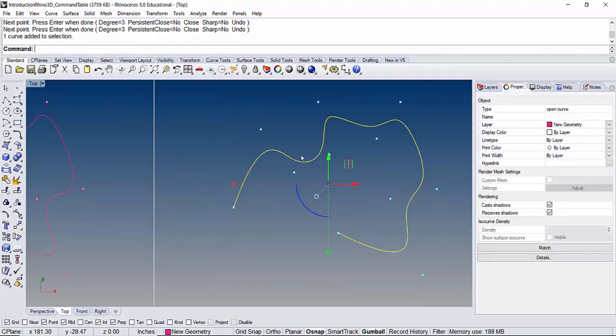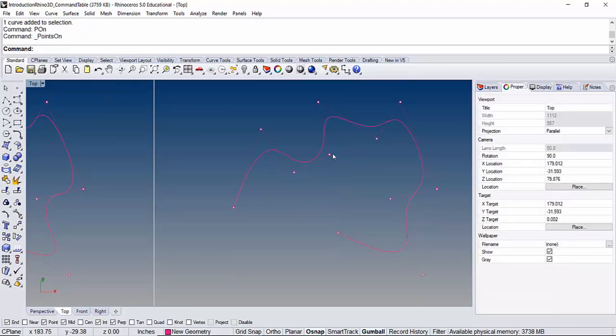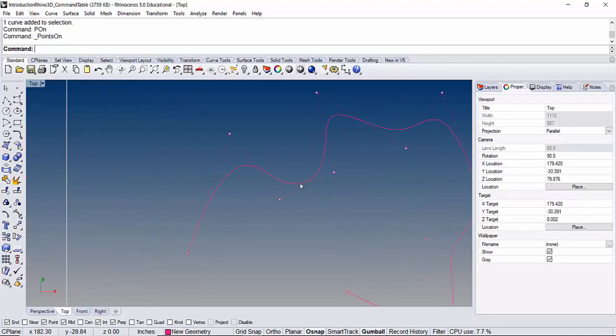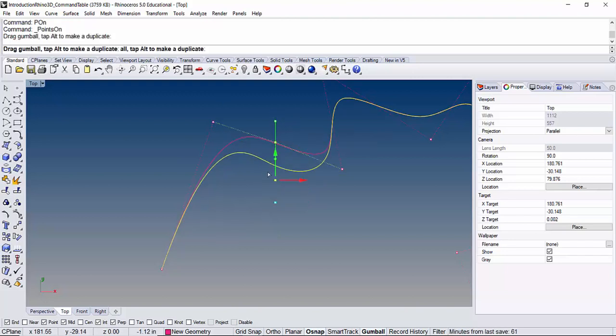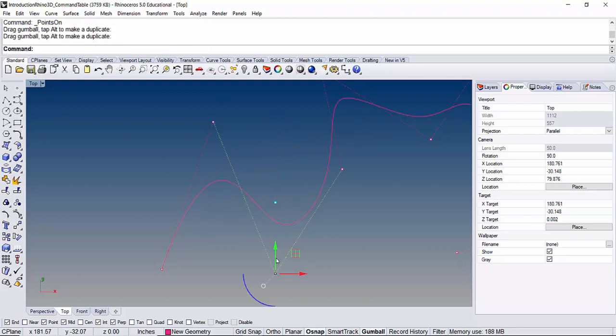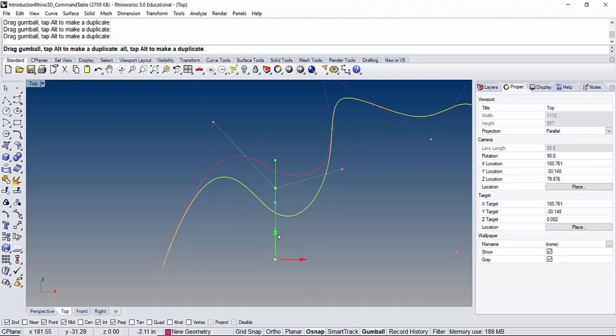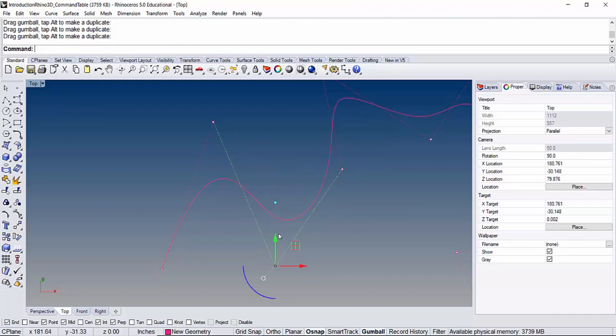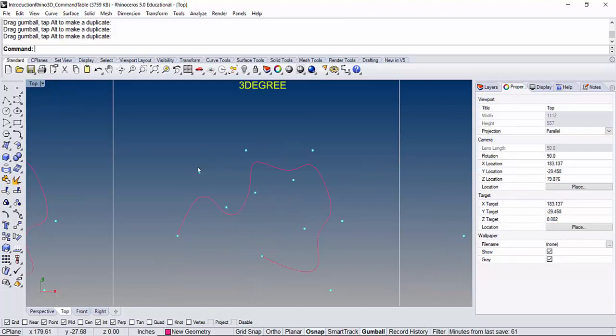So because a 3 degree, if I turn on the control points, it's smoother than a 2 degree, actually for every segment, there's 3 control points that are significant to the shape. So if I start to move them around, you could see that your geometry is not really going through these control points, but it's like when you're controlling a doll with a series of strings, right? When you push one, all the other ones are also becoming affected. So they become really a more averaged out curve.